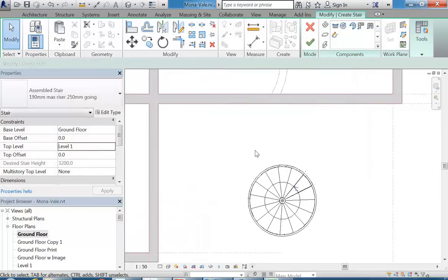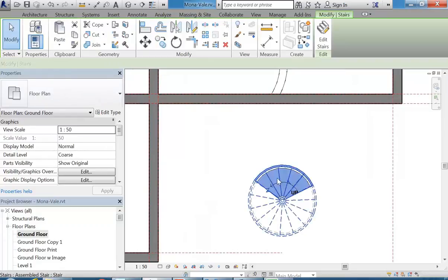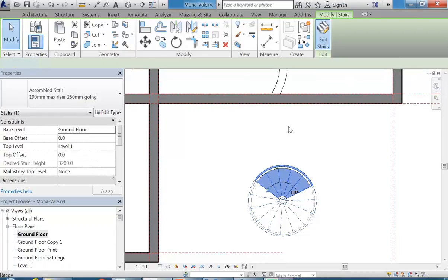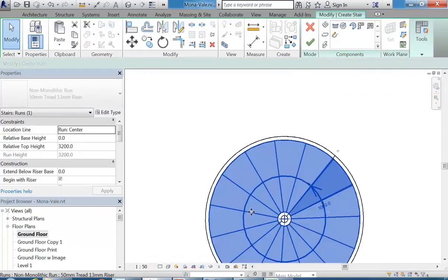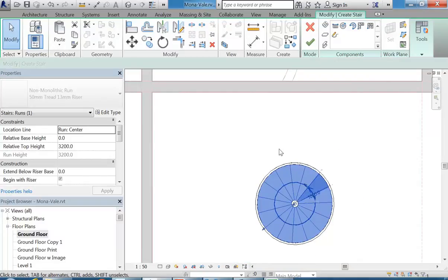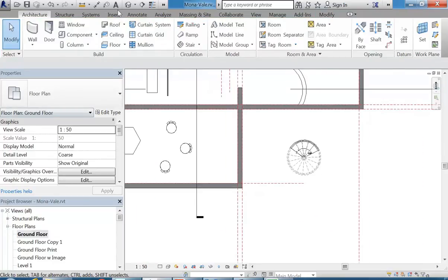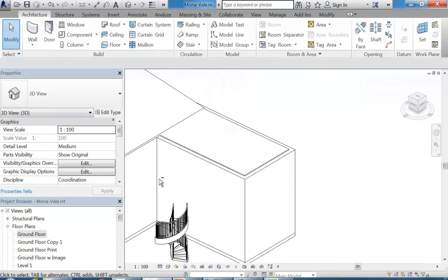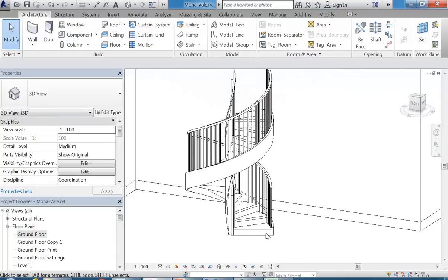So the reason I don't recommend using this one initially is because when you go to edit it, it's really different. If I go here, edit stairs, notice how there's no sketch there. There's no 2D lines. You can edit it, but it's just more difficult than if it's a sketch. But for spiral stairs, really handy, because that's very difficult to make with Stair by Sketch.